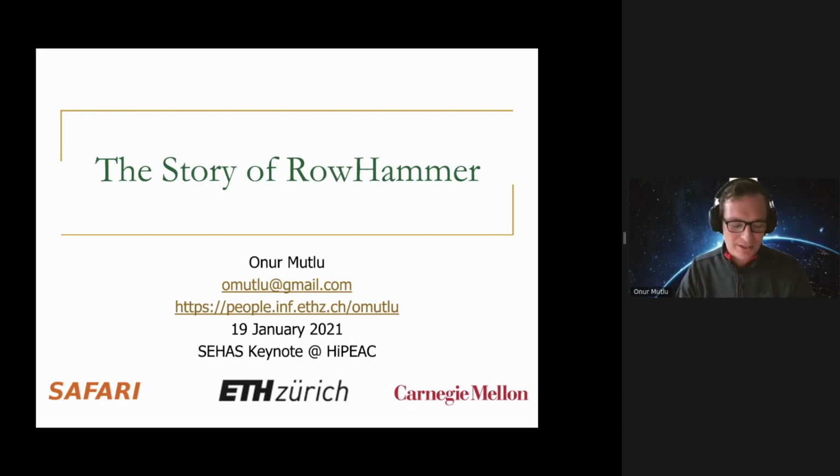Basically, I didn't want to go into the memory technology over here. Memory technology is really very, very different from logic technology. So what you mentioned over here does not apply as much. But if you go into the guts of how DRAM is implemented, there are not many options that you have internally, and all of the major manufacturers have essentially converged into some technology internally so that they can manufacture the capacitor without a lot of leakage.